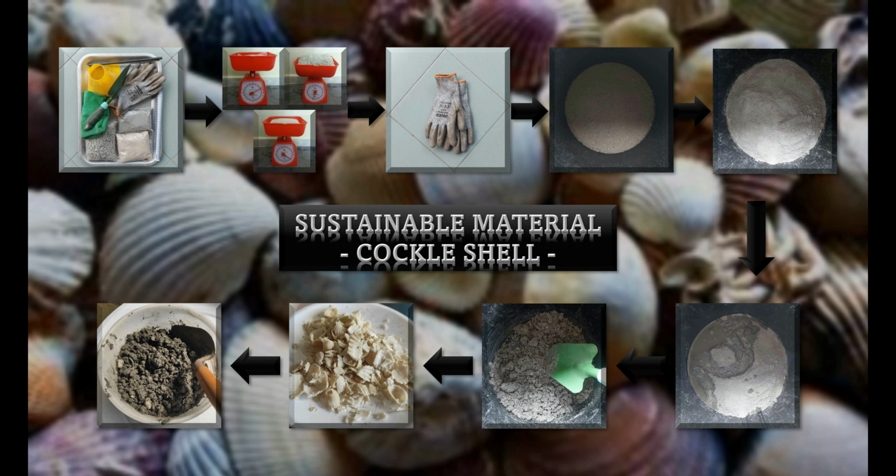0.689 kg of fine aggregate is put into the container and spread evenly. 0.328 kg of cement powder is put into the container and spread evenly on top of the fine aggregate. 0.1785 kg of water is added into the container. The fine aggregate, water and cement powder are mixed intimately using a spade, by turning over and over repeatedly until the color of the mixture is even. Then spread out the mixture evenly.